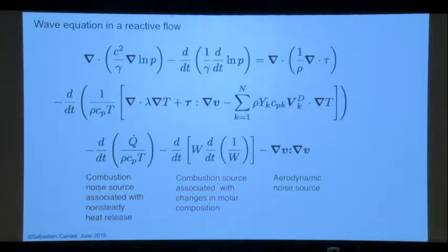And then we have a term which basically is the combustion noise, which is here, associated with the non-steady heat release. In addition, you have terms which are just associated with the fact that you have changes in the molar mass. And this will produce sound. Because you change the molar masses, and so the volumes are changing, and this produces sound. And then you have a term which is aerodynamic sound. It's essentially the gradients of the velocity, double scalar products with the gradients of velocity.